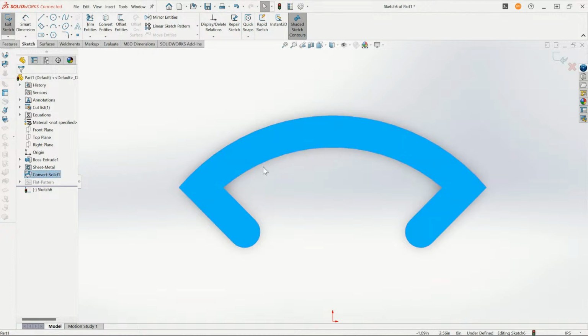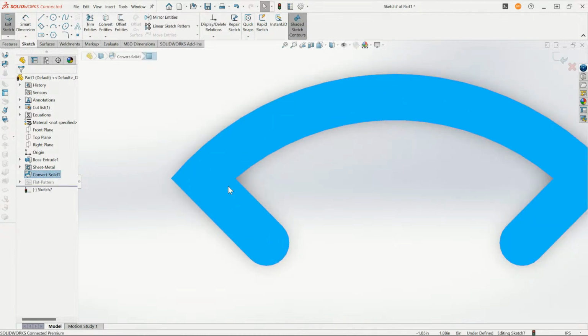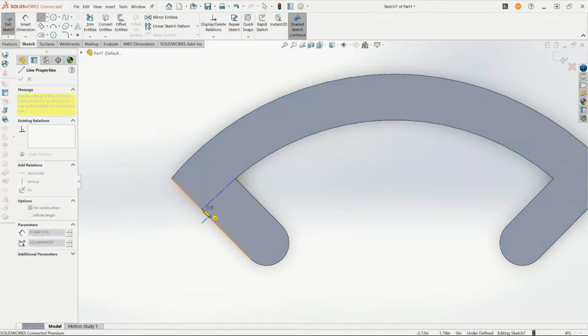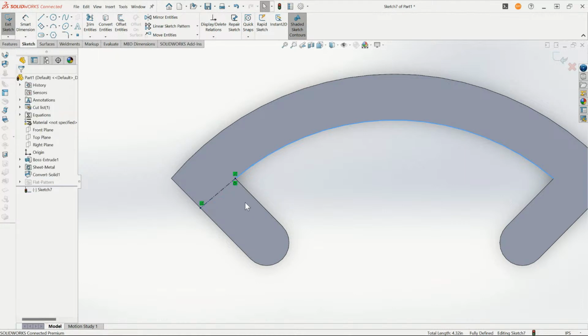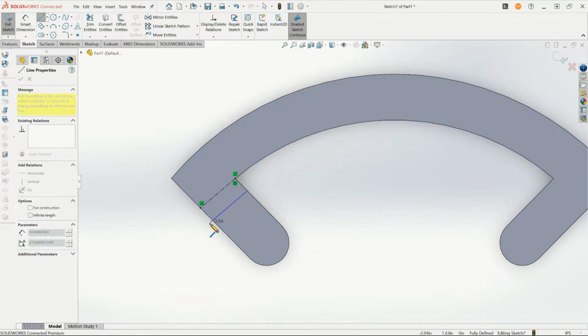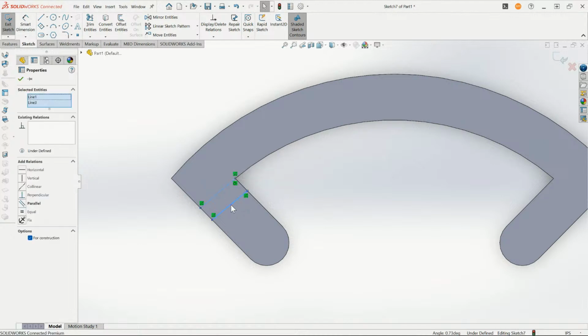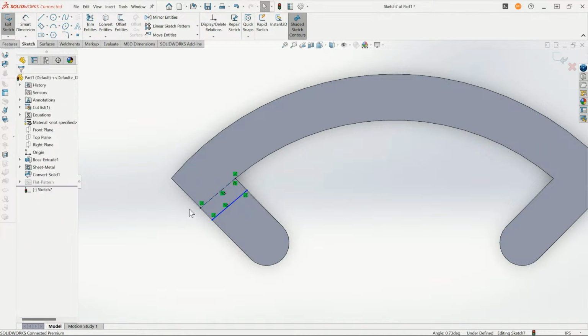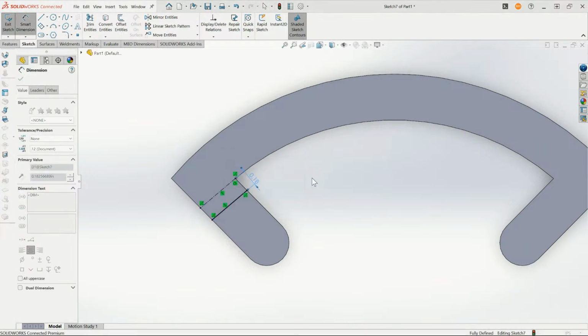So, and the bend is actually quite simple. We can do a sketch just like we normally would. And let's say we add a line right here. We want to make this tangent to that bend there. Yeah. That'll just be a construction line. We actually want the bend to move a little bit forward so it doesn't interfere with the inside of our tangent line there. So I'm going to make these two parallel, add a bit of a gap there. Let's call that 1/8 of an inch.